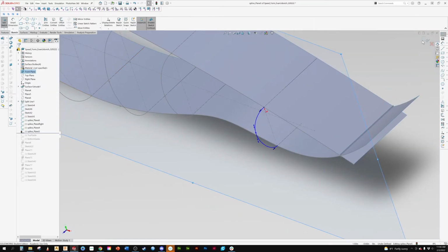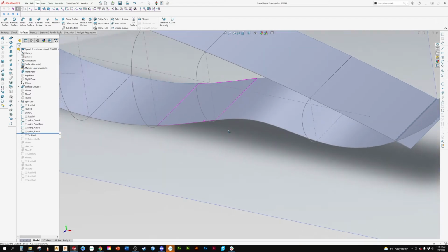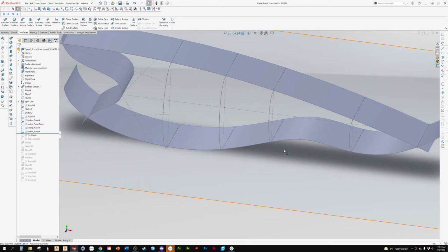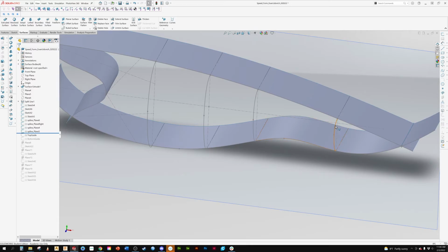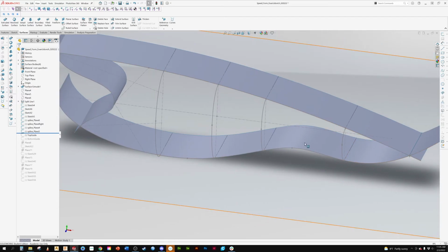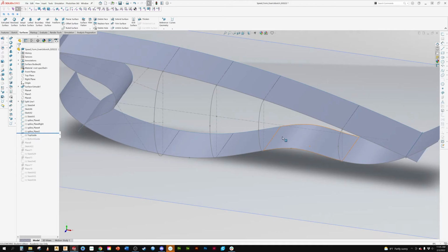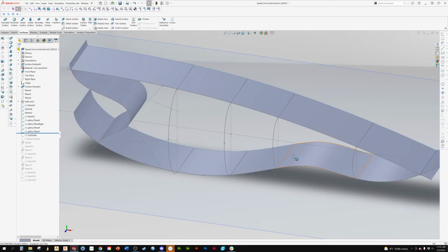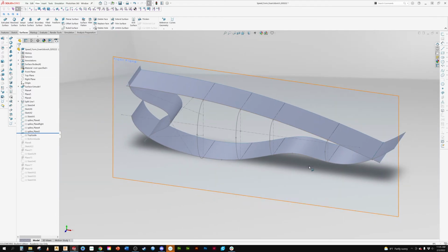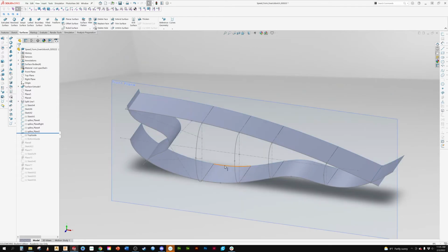Now, we're going to exit out of this. When we first looked at the surface model, the individual had created a three-sided surface all the way down to here. So we want to avoid that, and later on in the project, I'll show you one of the best ways to create three-sided surfaces when you're doing 3D modeling, to help remove the baby's butt that we had seen. So now that we have our surface edge, our bottom surface edge, and all of our control points, we can come in and create our first surface.